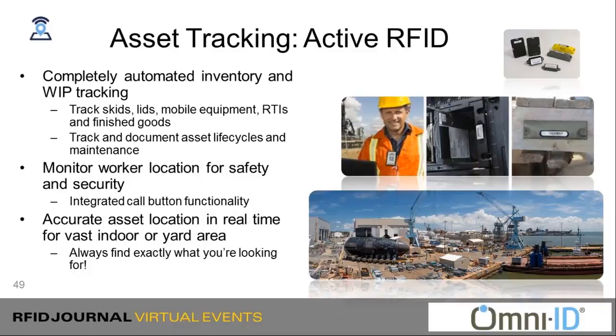You just don't need as much infrastructure to cover the long distances when you can get 600 meters or even a kilometer of distance with the right kind of mounting and a long wavelength. So active RFID outside tends to be dominated by longer wavelength, smaller frequency protocols. We use 433 quite a lot. It really is very good for that. It also penetrates water. It gets around metal very well. So it's really good for those environments.